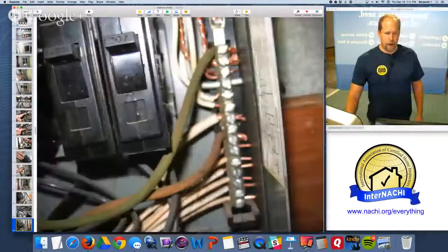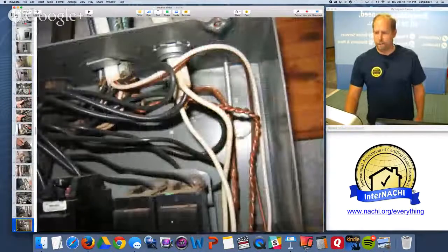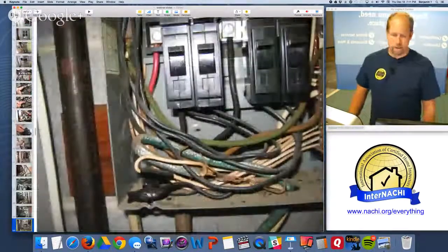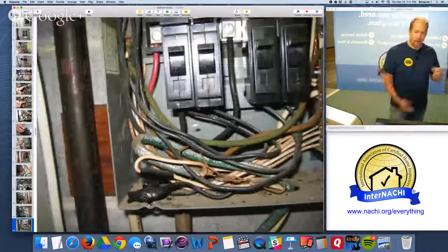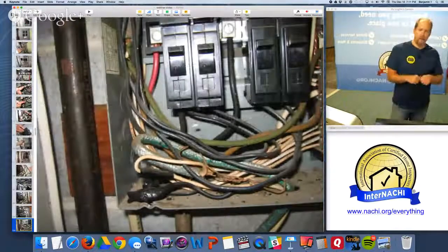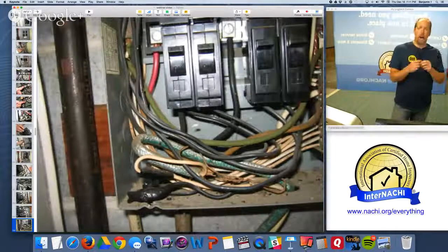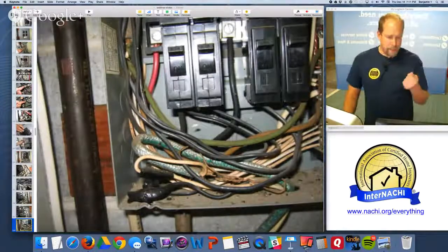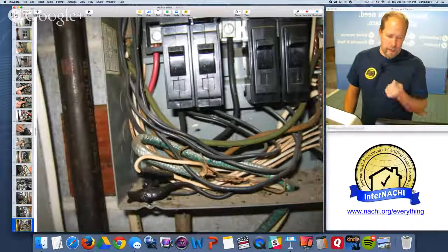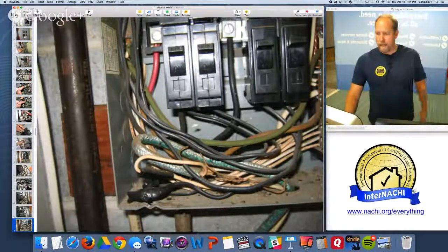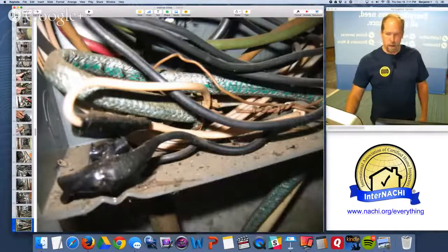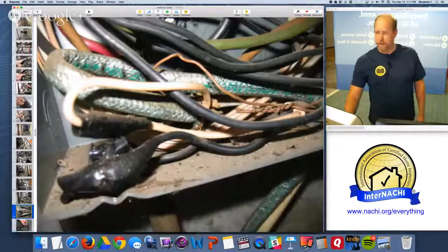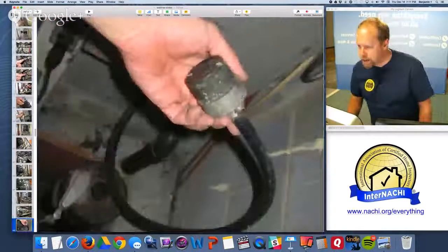There's a double tap breaker there. They just need a lot of help here. There's grounds that are twisted inside, but there's improper wiring and connections on the inside. They're just using tape, and there's a lot of things in here. Missing clamps at the knockouts. There's some damaged wires.